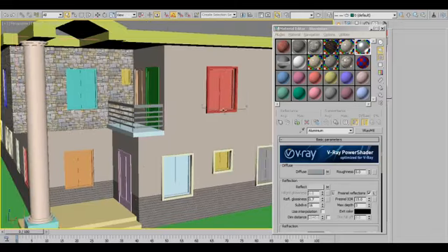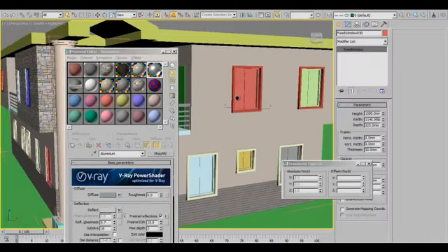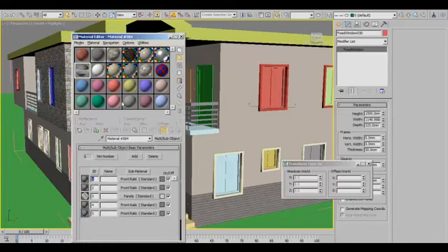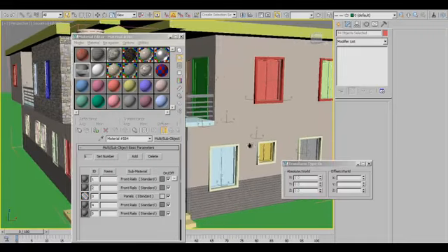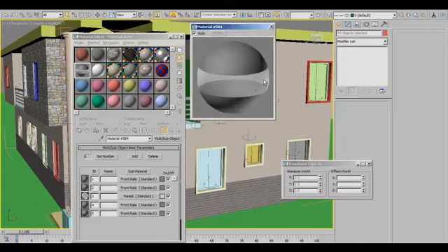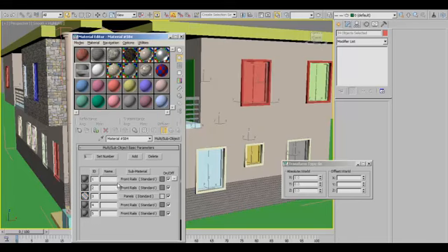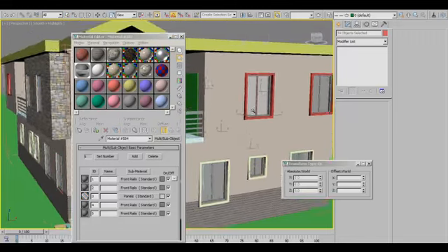And we can also do our windows, because we used AEC windows. We have AEC materials in our Max material, which is already pre-made, and once applied it automatically distributes the sub-object materials and places them well. So let's take a look, and I'll select similar, so it's going to select all the AEC windows, and I'll apply this AEC material which has 5 sets. So I can apply that, and it applies automatically.